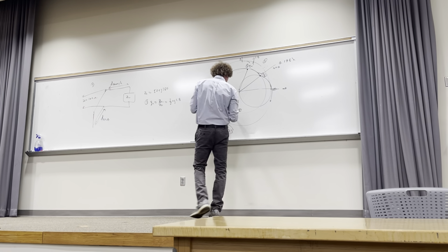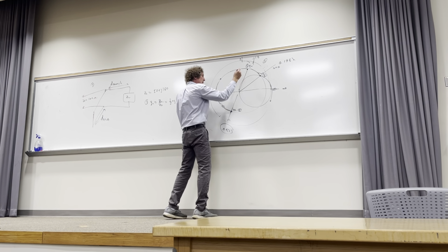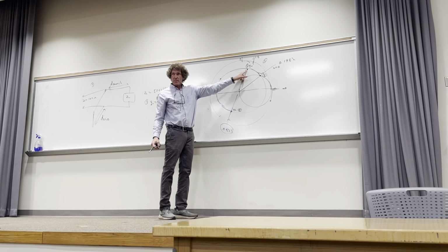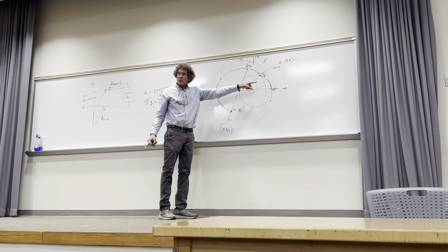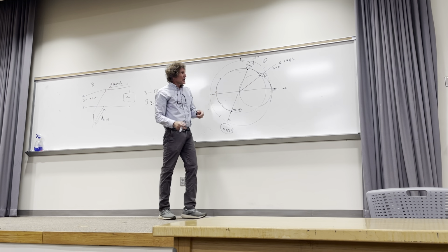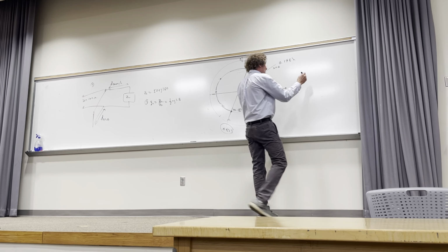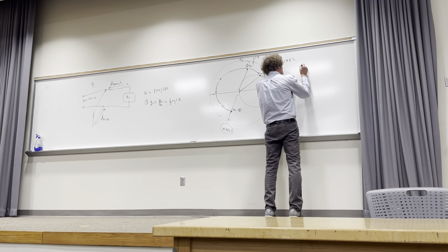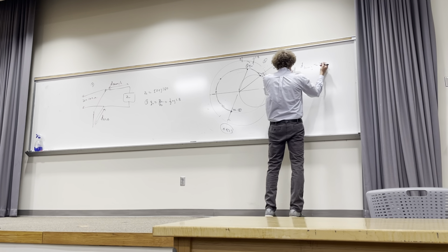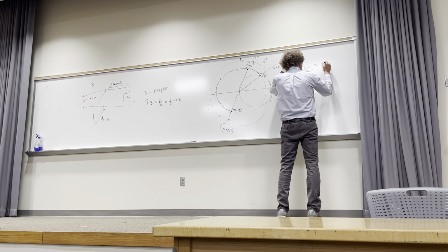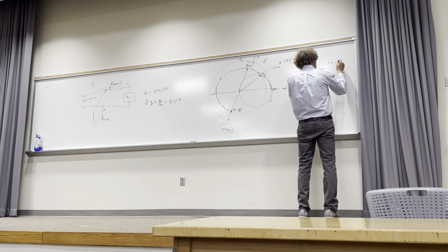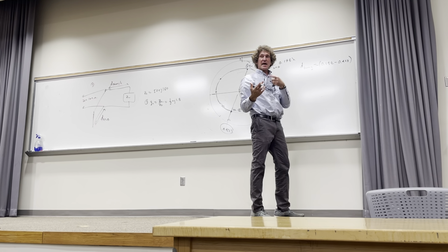Now, this is the thing that you have to understand. You came from here, you went to here. When I move from here to here, that's at least a quarter wavelength, right? So I know it's more than a quarter wavelength that I'm going to be moving. And how much further? The actual distance I'm going to be moving for D through line is going to be this point, 0.198, minus that point. But that's a negative value, so we add half wavelength.